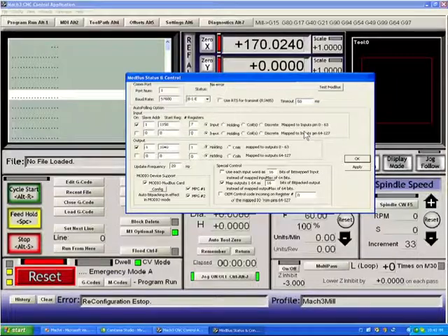Here we have a timeout that you can set to tell the computer to give up on a message if it's taking any longer than 50 milliseconds to get a response. And this use RTS for transmit on an RS-485 is to increase the transmission frequency to PLCs that are run by RS-485 converters. And that's it for ModBus.